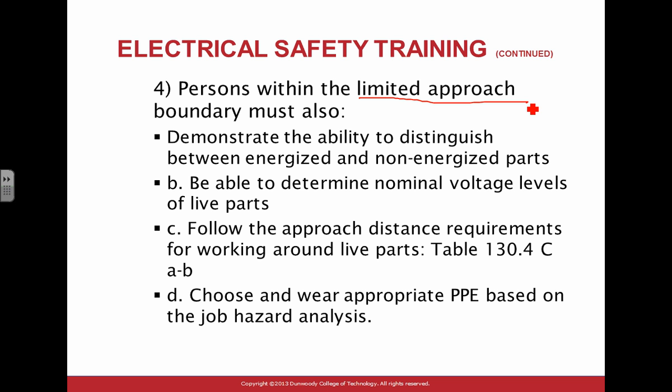I don't know how much you get into the control of the equipment, but I don't know how you're going to be testing a VFD or programming a PLC without verifying the presence of the voltage. Do we have voltage coming in? And it's not working. Well, what if the disconnect or the circuit breaker tripped on the other end? Maybe I should go verify the power, not just the control circuit. So you will be in a lot of situations verifying at least the presence of voltage.